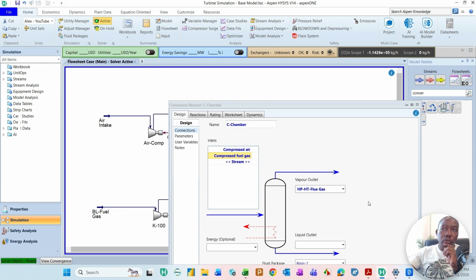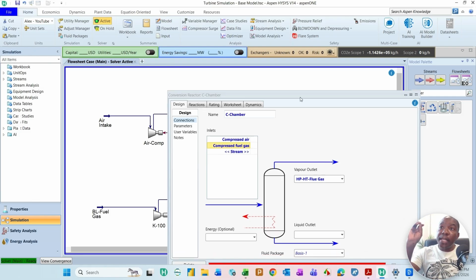But there's one other thing that you'll see, because that air intake is actually combustion air at the stoichiometric level, and we are using excess air. Most turbines actually use close to 100% excess air. You'll see those in the next set of videos that will follow on how we assess the whole turbine performance, including CO2 reduction, percentage excess air used for the combustions, basically the optimization part of this process. At this stage, we're just setting up the base model that will match the manufacturer's datasheet.